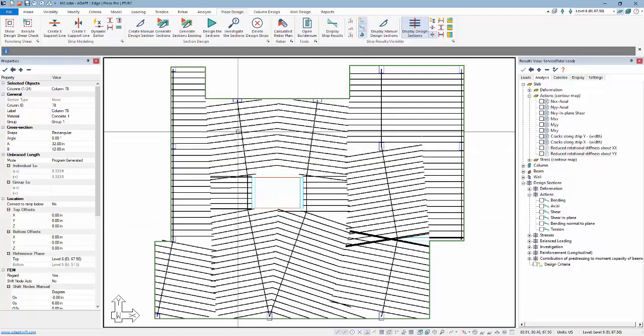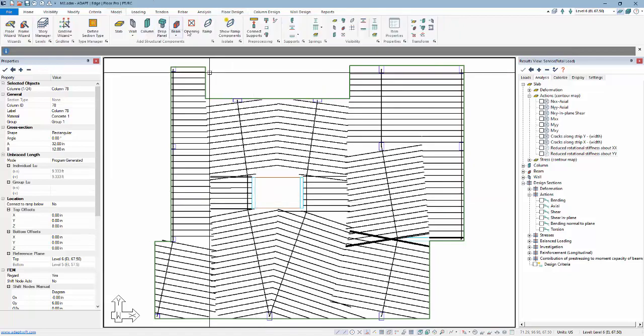So we were getting negative bending throughout most of this inner region of the slab in the model. It was essentially cantilevering off all 4 sides in that model. So we went back and corrected that. That was an easy correction. We just went to Model, Connect Supports, and that's a good lesson.